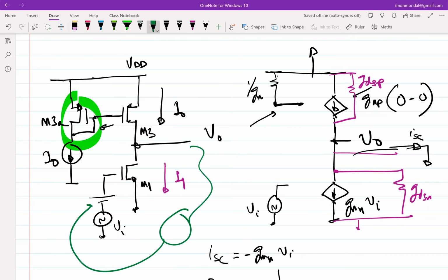We are more comfortable analyzing circuits in open loop, right? Analyzing circuits in feedback is slightly more complicated. So we try to break the loop and then find out its open loop transfer function always. In that A beta model of feedback, you try to figure out what A is separately. So this is essentially the purpose of figuring out A. So that's always the case.